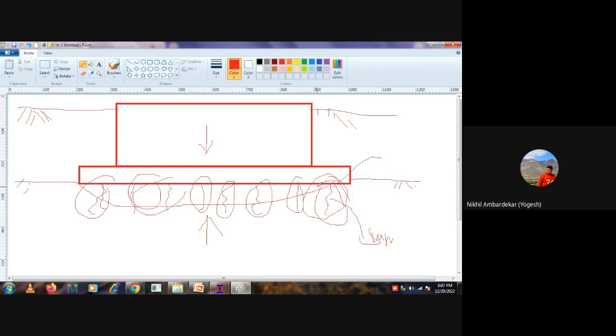4 mm, 10 mm, 25 mm, based on the load. Are you getting me? Yes, sir. So if that value is not given, we need to assume some deflection, and with that deflection, we can find out the value of the subgrade modulus of reaction.